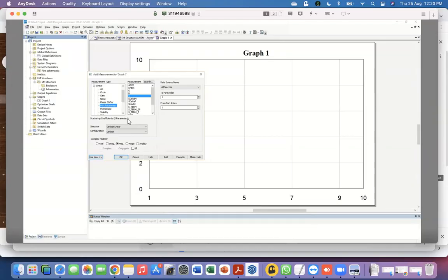And this is basically, as I was telling you last time also, it's similar to the scattering things you study in quantum mechanics or even in electromagnetic radiation, if some of you have done it. And essentially it tells you when a wave is incident on some structure, what is the ratio of ingoing to outgoing waves, what is the ratio of transmitted versus reflected waves or incident waves. So these all create various kinds of scattering parameters. It's usually defined in a matrix form. Here, of course, you refer to them with these indices.